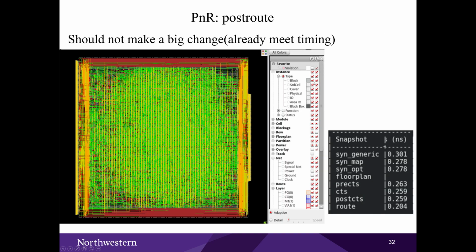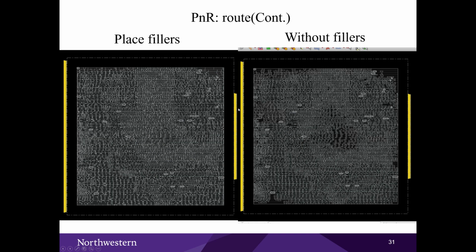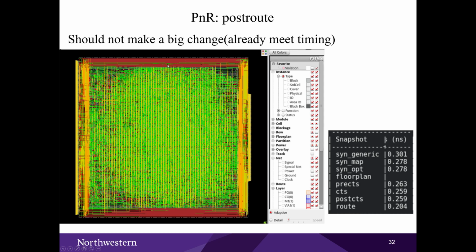And the post route function is pretty similar to post CTS. It just optimizes our layout, and because we made timing here, it should not make a big change. So we can see it's just the same as the layout after route.